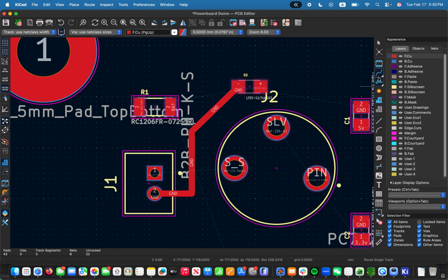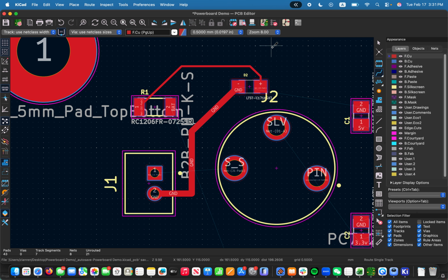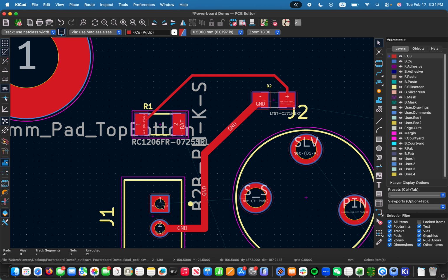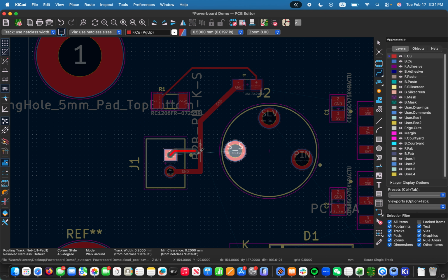and then let's do another trace. Looks like this R1 goes to this D2, and then I like to route a little further away from the components, just in case you accidentally break something, it's easier to fix. So kind of like what I'm talking about here. So you see that's going away, not touching that component. And then we will trace from, make sure you're clicking this routing tool every single time. Then now you see that you cannot overlap the same layer because these are both red wires. These are going to be on the same layer. So now we're going to have to go around.